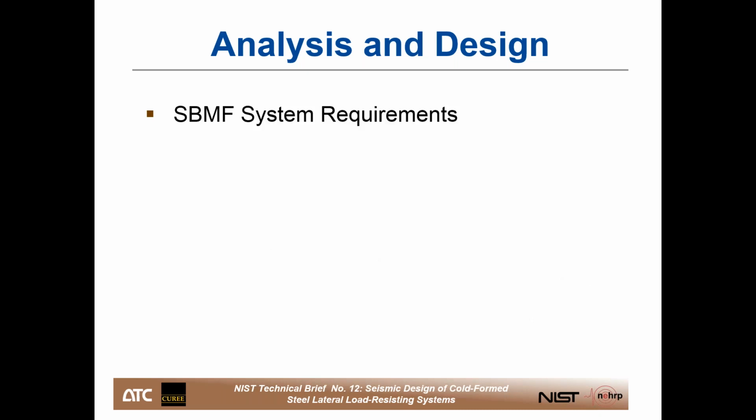So there's a number of system requirements for special bolted moment frames imposed in S400. And these are all based on the range of tested systems. So this is a system that underwent extensive testing, and because of that, the parameters for which you can design a special bolted moment frame are all boxed in by those test limits.